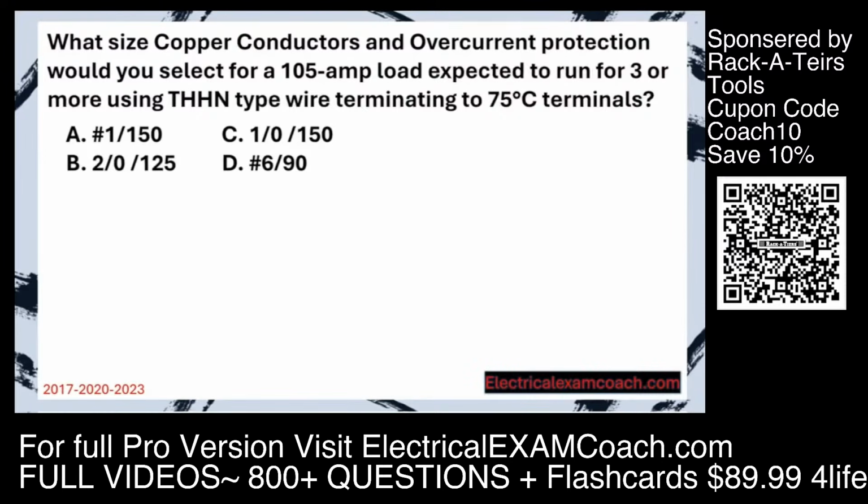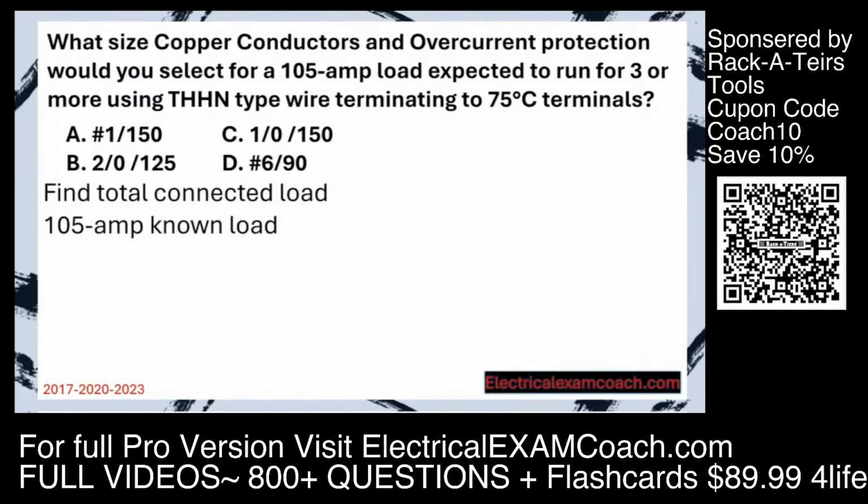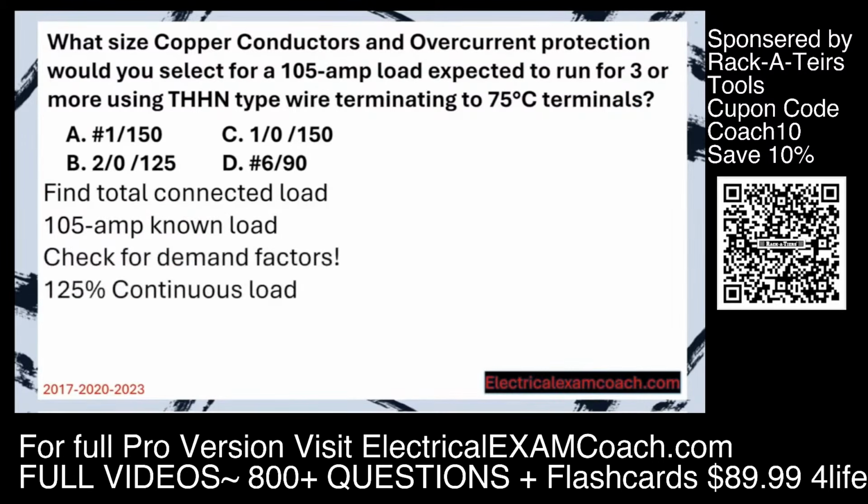What size copper conductors and overcurrent protection would you select for a 105 amp load expected to run for 3 or more hours using THHN type wire terminating to 75° C terminals? Step 1, find the total connected load. 105 amps is our starting known load, but we must check for demand factors. When we look, we find that we have the 125% continuous load rule, so we do our math. We take our original starting known load, we multiply it by 1.25. That gives us a new known load of 131 amps.